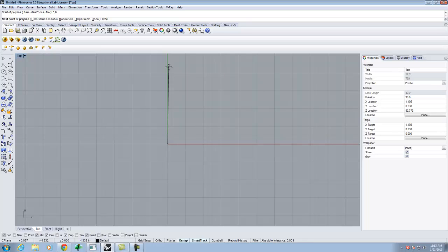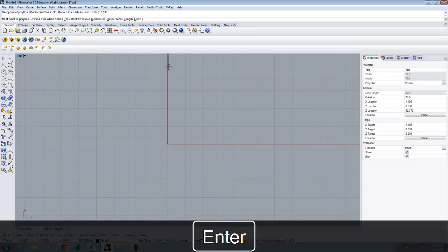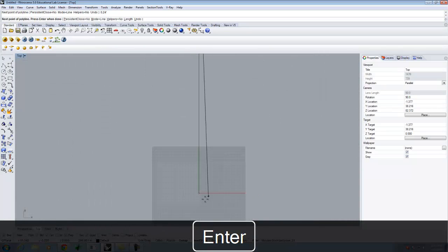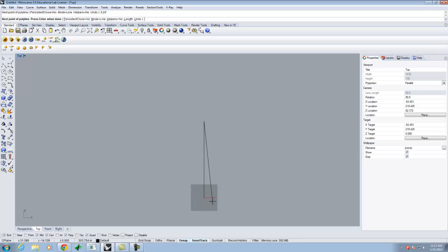So when I type it in, I'll type 0, 24, and then a little apostrophe for feet. When I hit enter, I have to zoom out so I can see it, but we can see that I've gone up 24 feet in a straight line. The next thing I want to do is go to my right 12 feet. So if we're back here on the graph, I want to go in this direction 12 feet, so it's going to be a point out here.